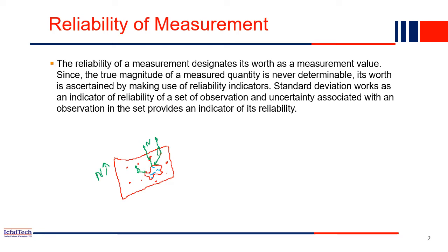All these parameters we are now measuring. From different distances we do all these things. From all control points, basically we measure distances as well as angles. Once we have all the measurements, we come to our office and prepare this plot. We first set the control points on the map, and then we locate the lake with these measurements and the angles.